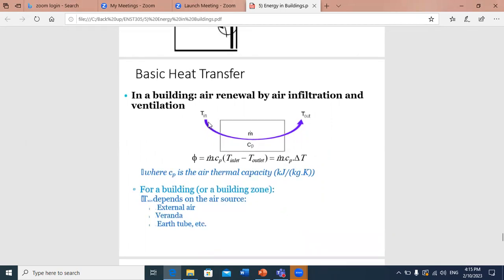And to calculate the heat exchanged by infiltration, it's simple: you have a mass flux of air that is carrying heat. We can calculate the heat carried as m dot Cp times delta T, where Cp represents the specific heat, m dot the mass flow rate, and delta T the variation in temperature. We'll also discuss in the next chapter how to control such issues.